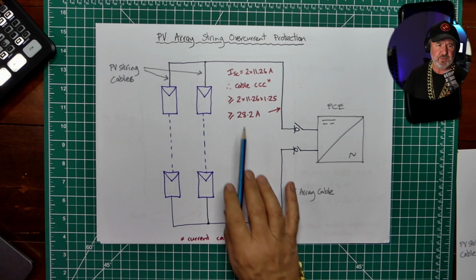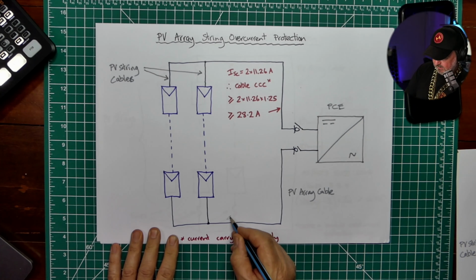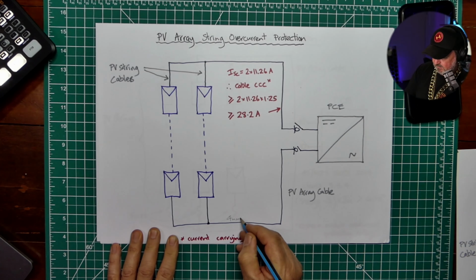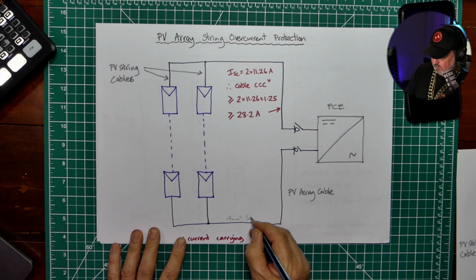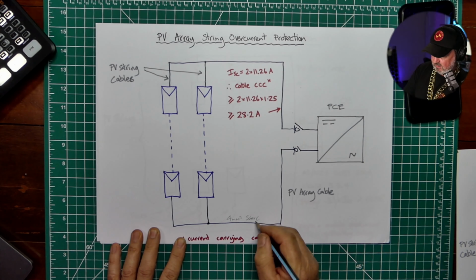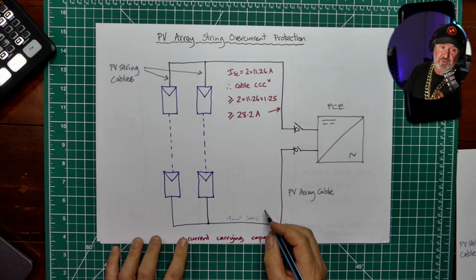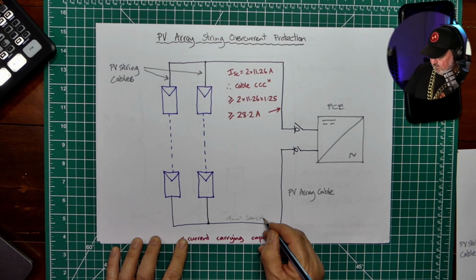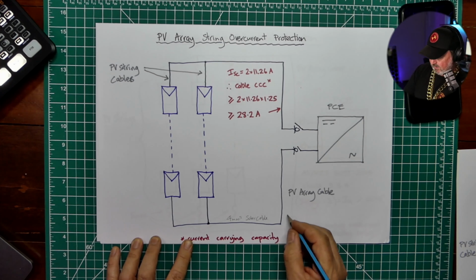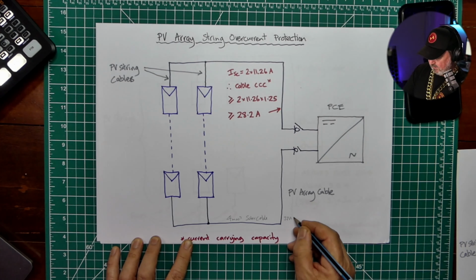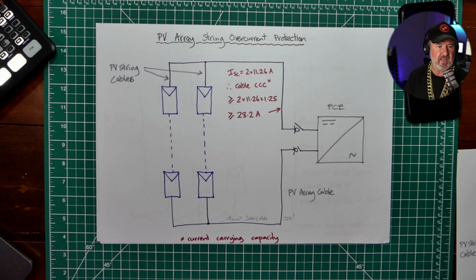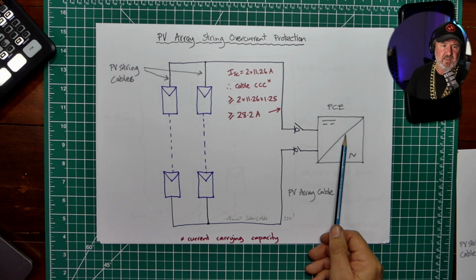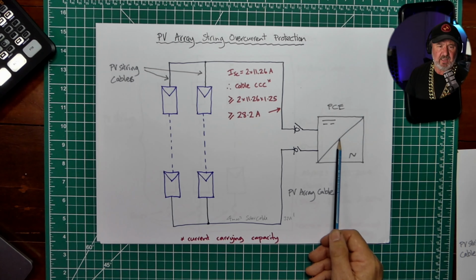And we already saw that, for instance, if we're using 4mm square solar cable, it would be good for enclosed in conduit against the surface for 37 amps. So no problem there. 37 amps. That's fine. Okay, so that solar cable's plenty big enough, and we've chosen an inverter that can cope with an ISC of 37 amps on its input.